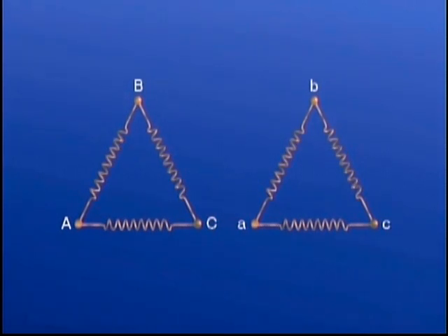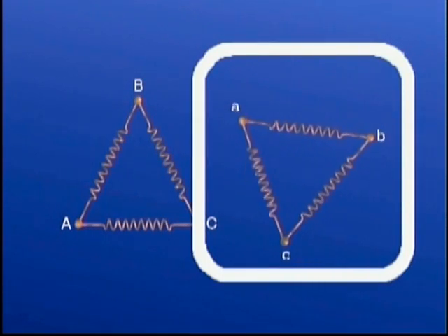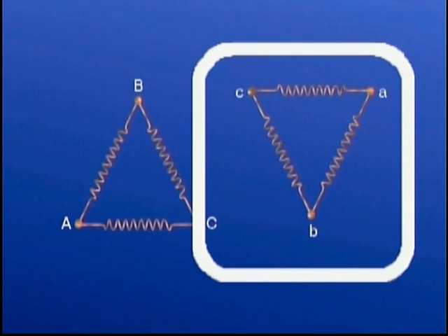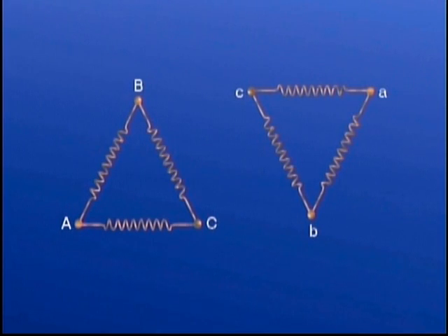There are many ways of making a delta-delta connection. If we were to rotate the secondary phasor diagram 180 degrees, for example, we would change the angular displacement. The delta-delta connection, according to this arrangement, would produce 180 degrees of angular displacement between the primary and secondary windings.